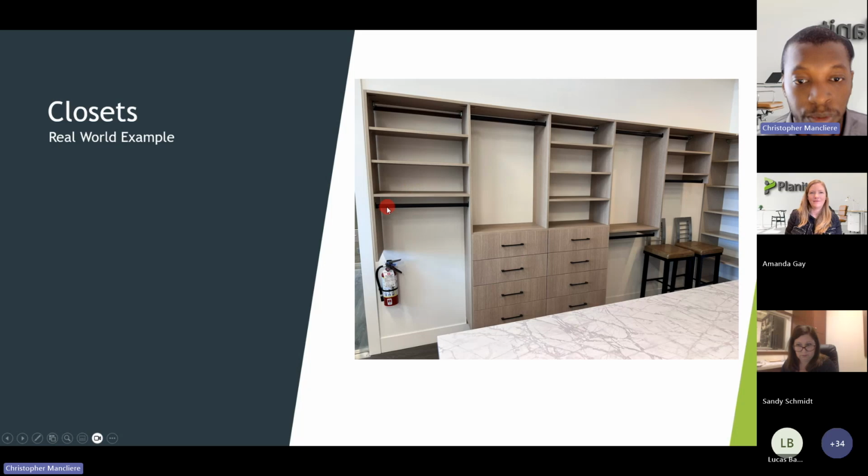And if you need to include, for example, closet rods, wire baskets, drawer guides, this is all done using a 32 mil system on the panels. The 32 mil system is an essential thing in the closet industry. It's the fact that you make it very modular, so you can readjust or modify the whole configuration of a closet directly on site. So it's easier for the client and user to be able to move their rod up or down or readjust the shelf or the fixed shelf if they, for example, decide to reconfigure it. So we don't have to basically start over and buy a new closet. We just unscrew and move things around and reassemble it.